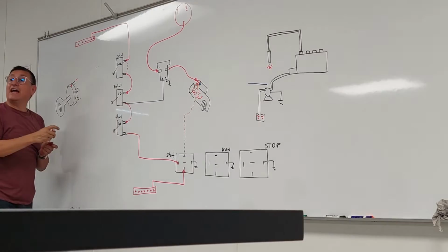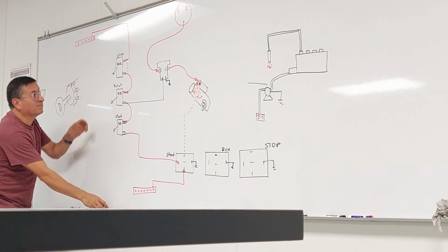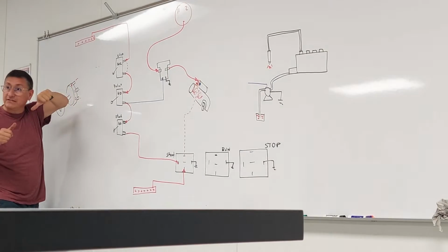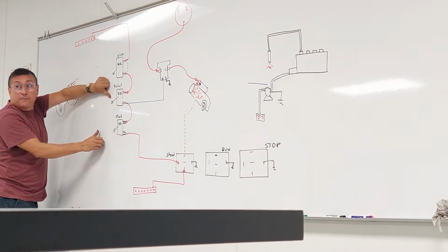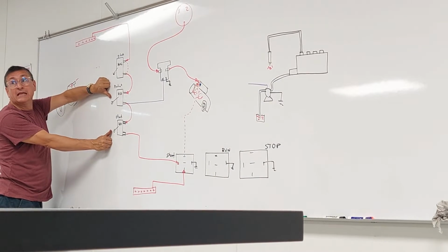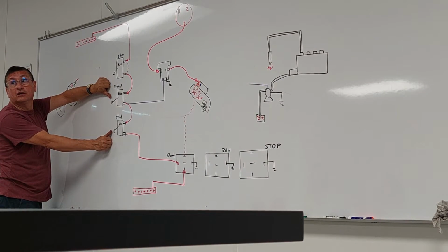Look at this. I am going to start the engine. Pay attention. I press the preheat. I keep the preheat pressed. And I press start. And now the start motor is spinning? Yes or not? Yeah.